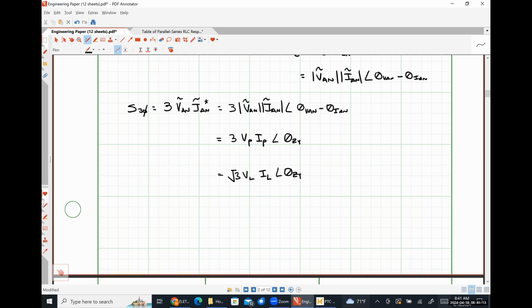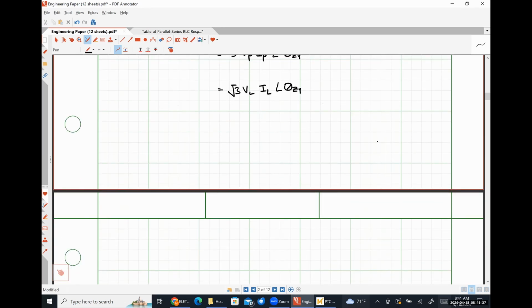That's not the thing that we're actually looking for. If we wanted the voltage drop across the transmission line, we would usually just say, what's the voltage drop at the source, and then subtract the voltage drop at the load from that, and that gives us our answer. So we never do a whole lot of calculations with what's actually going on in the transmission lines. It's just kind of a side effect of things. I'm not saying we're going to ignore them by any stretch of the imagination, but all of that information is buried in the other stuff that we're already doing.